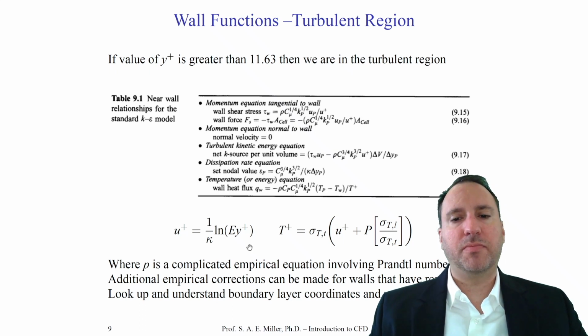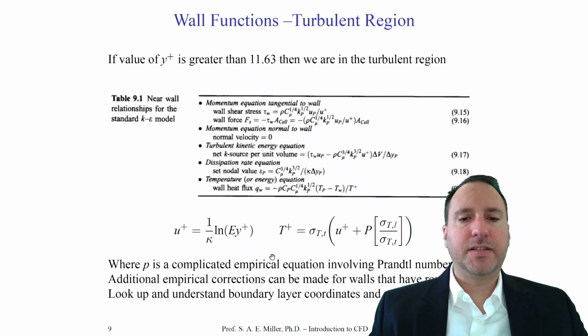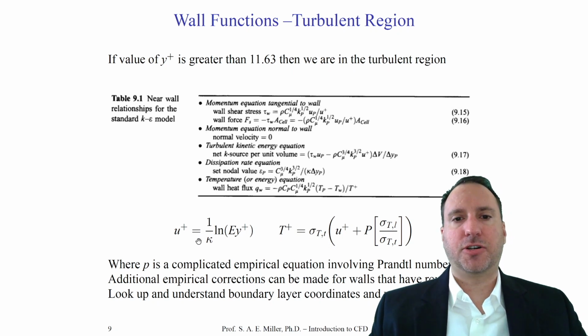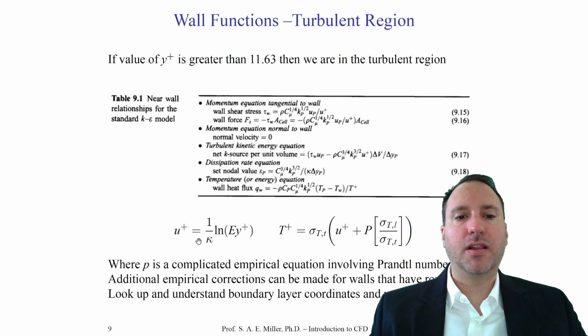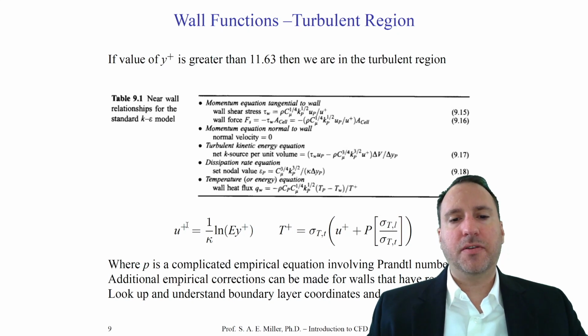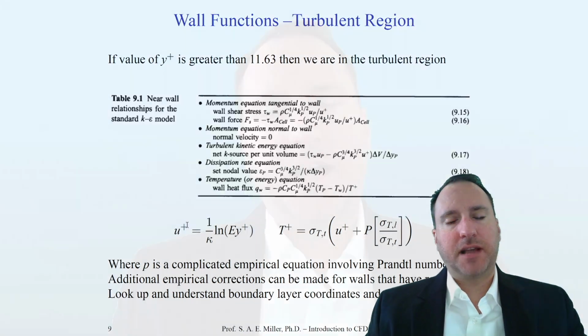Almost all turbulent boundary layers that we know of have this particular form in nature. And so we are forcing our CFD solution to correspond to the collapse and similarity of the solutions we find in nature. It's a very powerful thing. Now, the wonderful thing about this, of course, is that it will save us great computational expense.